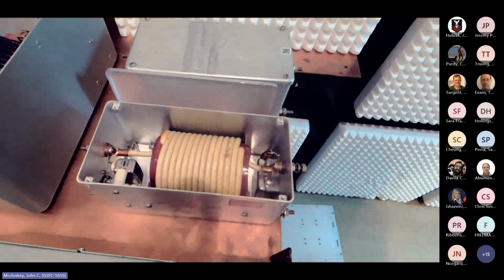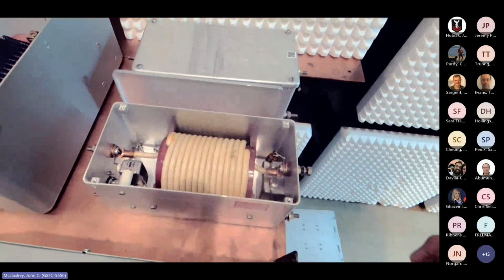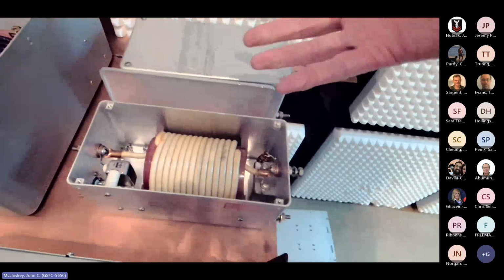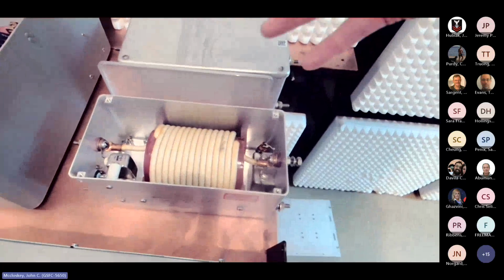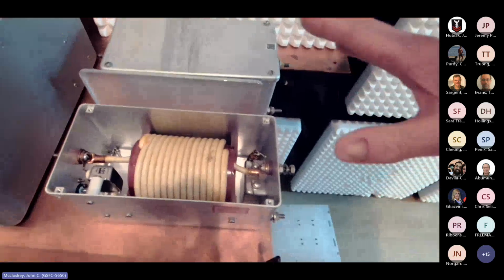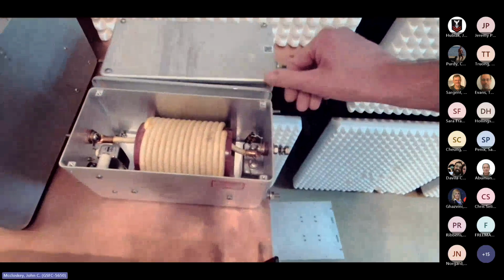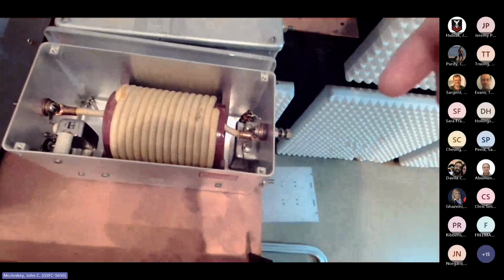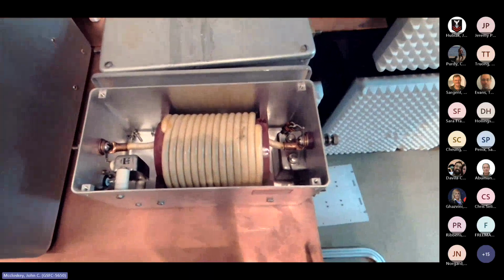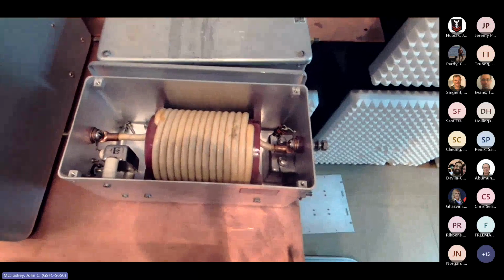But 50 microhenries is a pretty big spacecraft. We're generally not dealing with anything that big. So if you've got on the order of 100 nanohenries per meter running maybe 10 meters, then 1 to 2 microhenries is something a little more realistic. So bear all that in mind when you pick any kind of impedance network for your conducted emissions or for your whole test campaign. Really pay attention to how well that's representing the real impedance that you have on your platform.